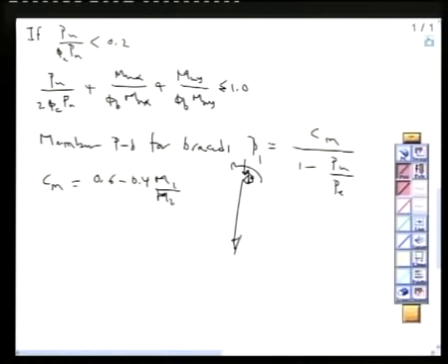The reason, if we have this and we got this single curvature, and this is M and this is M, for sure these two bending moments will give you a bending moment diagram of this shape in the compression side. Now this bending moment will cause deflection of this order, and for sure this axial load P is making an additional P delta, which will make the moment inside the member larger.